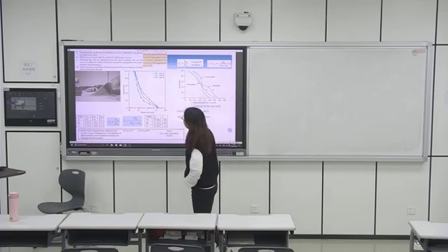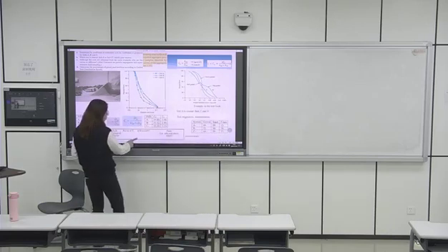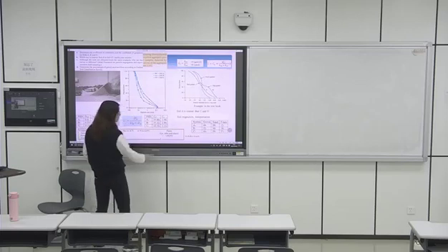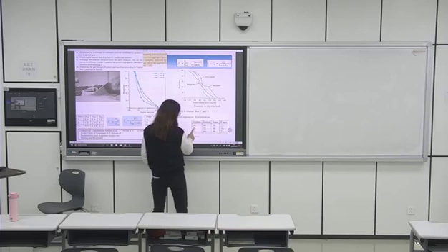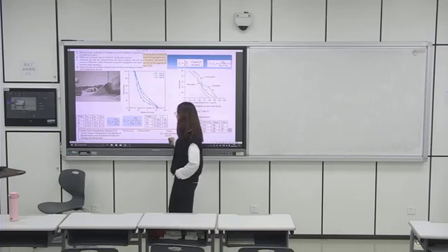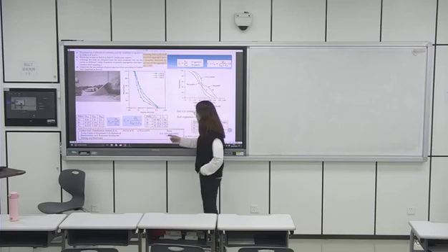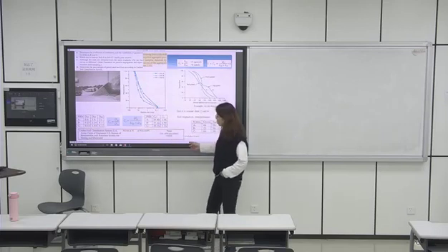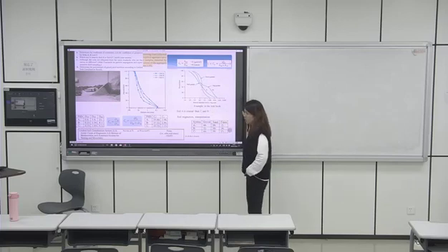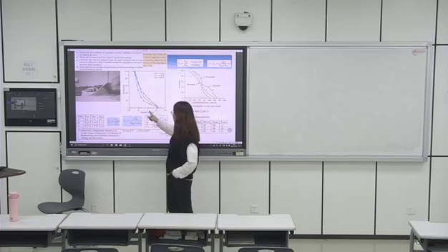The final one is to determine the percentage of gravel, sand, and fines according to the Unified Soil Classification System. We have the unified classification system. This is for gravel, sand, and fines. Then just define soil A, B, C by gravel, sand, and fines. For example, for the Unified Soil Classification System, fines means particles less than 0.075 millimeter, right? Then go to this figure to find the 0.075.